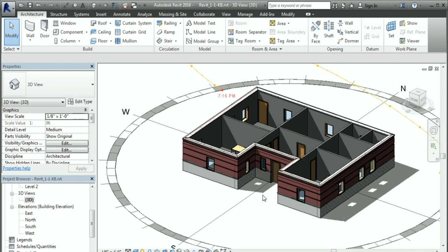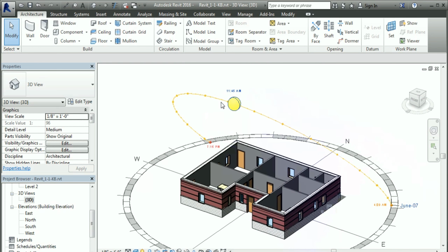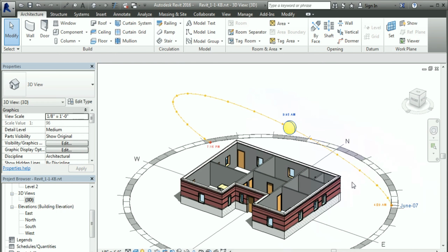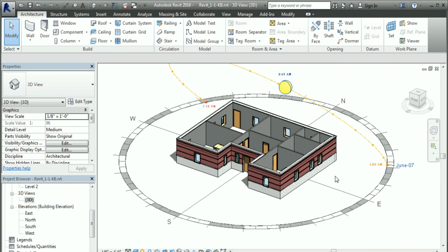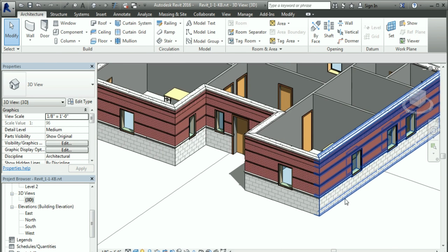Click on the sun and change the time by dragging it. So we pick and then pick again to drag it around to 7:45 a.m. And we can change this to 9:45. You can just pick in that blue text and change the values to adjust the sun as well. All right, let's do a zoom fit and zoom in and out with our wheel. ZF to go back out.